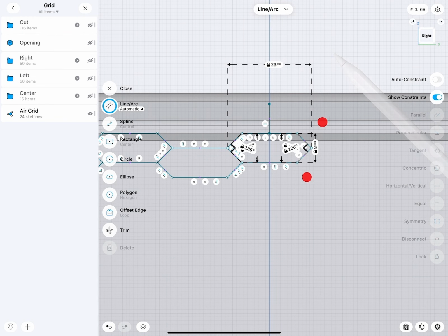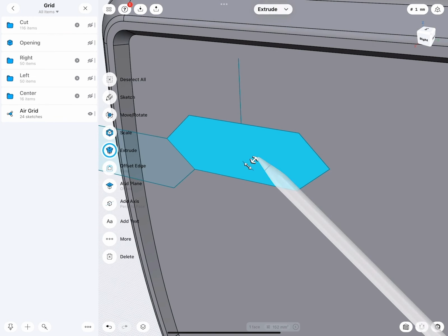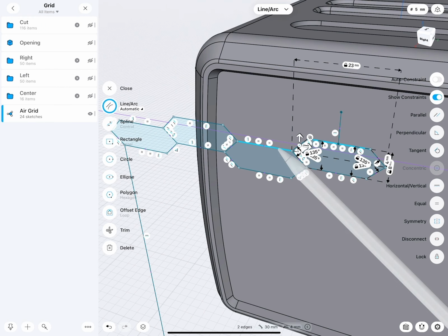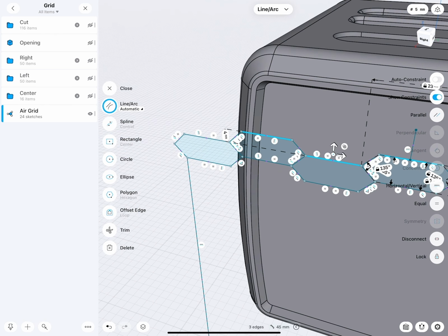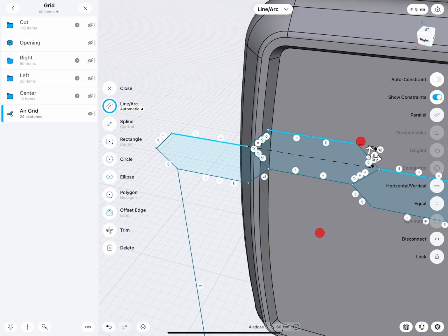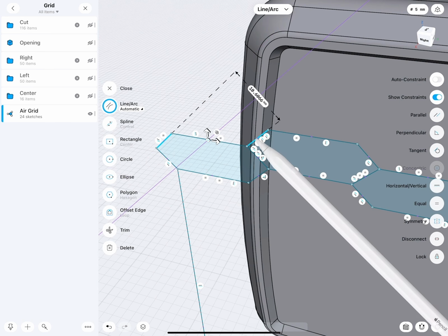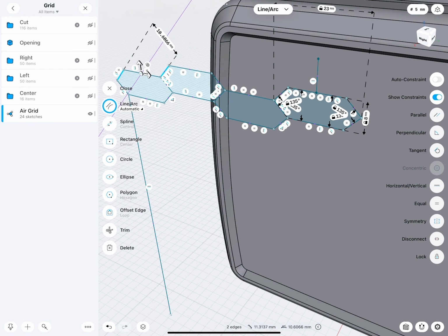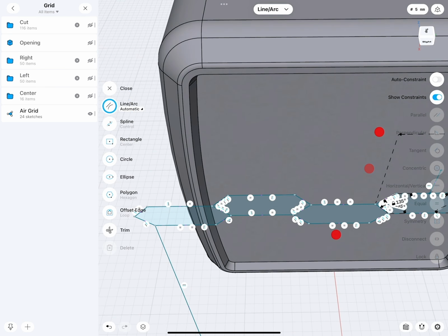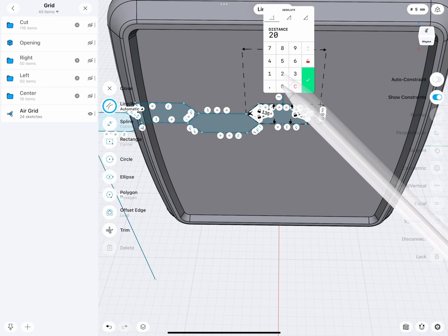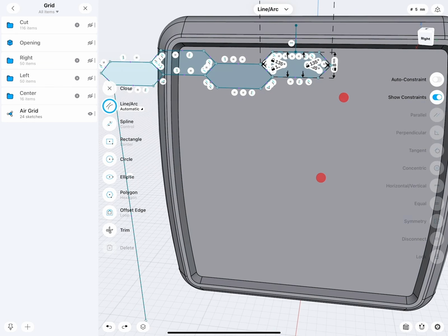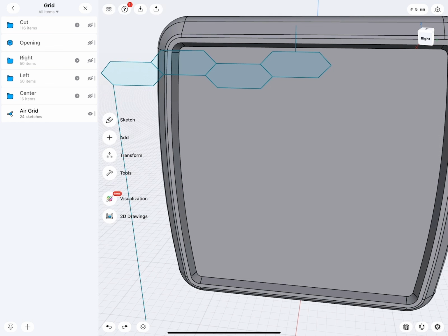A center line, then the geometrical elements to get everything to be parametric, because a sketch solver has constraints. Logical lines are equal. Parallel, horizontal, too. So these lines are, for example, parallel to this one. So this allows me, when I now select this and make this 20, well, the whole thing updates. If you look at that sketch, you will see that's the way how this is set up.